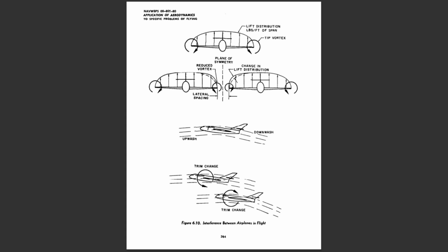Adequate clearance and proper position must be maintained by the pilot of the receiver, for a collision possibility is enhanced by the relative positions of the airplanes. A hazardous condition exists if the pilot of the receiver has excessive speed and runs under the tanker in close proximity. The trim change experienced by both airplanes may be large and unexpected, and it may be difficult to avoid a collision.